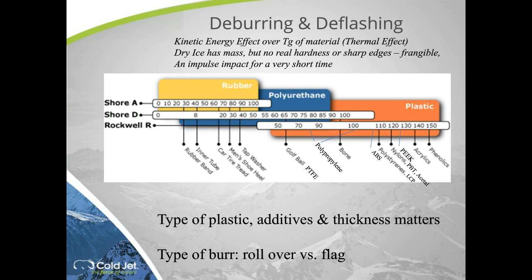For those that are softer, yes, you can dwell on it. You can get to the glass transition phase of that particular plastic with the cold or the dry ice. But it's going to take a little bit of time. So you're probably better off for that particular one to tumble it with some liquid nitrogen or another actual cryogenic deflashing technique on the softer resins.